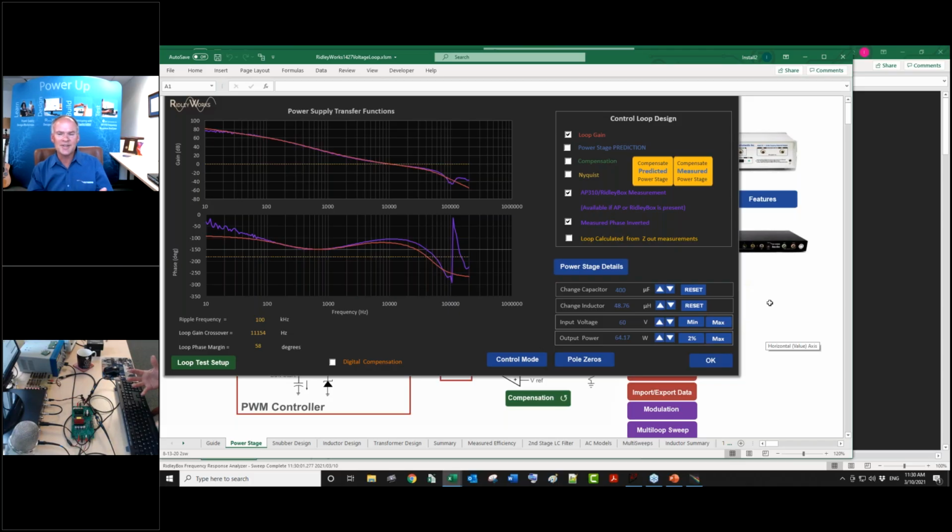If you're building a class D where the inverter is kind of a quasi DC, you can actually set it at a DC point and measure the loop at all points. So that can be a valid experiment. If you look at the input PFC, the current loop on the PFC can be stable at the top and unstable down the bottom.